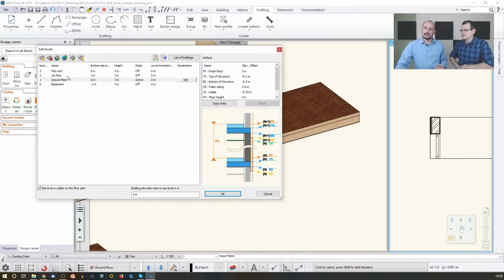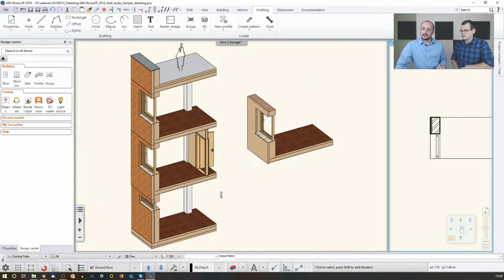Yeah, so actually you can see it's appearing here. And when I modify it, let's say it was not correct, I forgot to set it up, so I need to change that. Sorry, it should be 35. That's what I wanted to say. Okay, so it's 20 centimeters smaller. So I just say okay. Then the software updates that, and if I already create the whole building with the same setting, the whole building is updated now on this level. So this is not something that you have to update manually for every single wall.